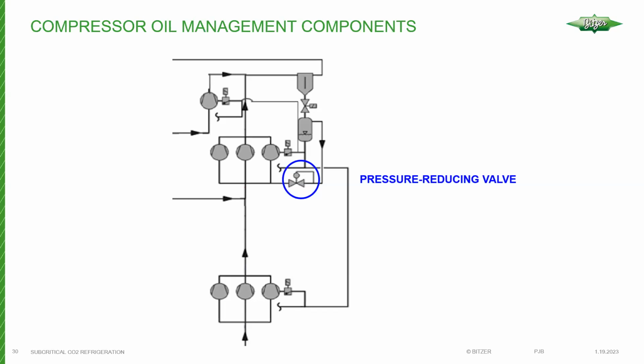So what's actually happening here is this will be your medium temp. For example, this is part of a booster system, actually, which we'll be covering. We'll be taking a look at that on February 16th in more detail. We've got two circuits, and so this one is vented to the medium temp circuit. So what this valve does is it looks at the suction pressure of the medium temperature compressors, and depending on its setting, it'll be set for, say, maybe 20, 25, 30, 35 psi, higher than the suction header pressure.